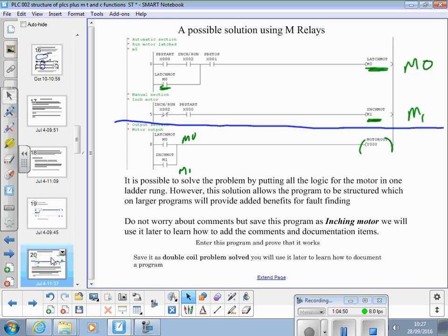Usually it's going to be something to do with the outside world. An input's not on, made or something, a limit switch is not working, the sensor's not given an input. Very rare is it an error in the program if that's been well tested in the first place.